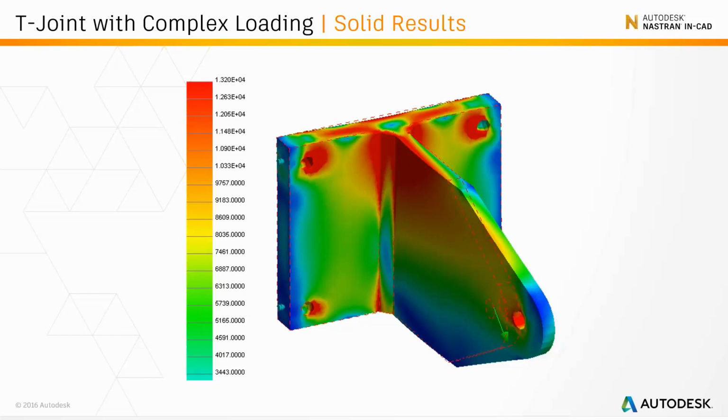It's clear to see that the stresses are dominated by areas where sharp edges are present, like those on the chamfer, suggesting singularities. The stresses are spread out into the face of the weld, so how realistic is this? It's hard to say. Solids, though, provide a very skewed look at the weld because of everything that's going on.